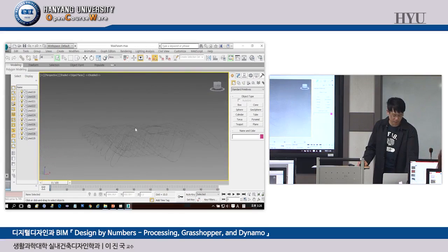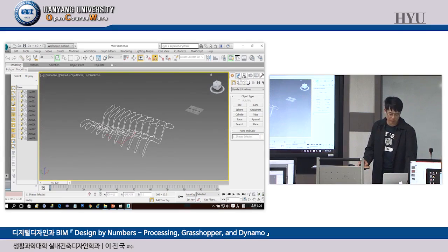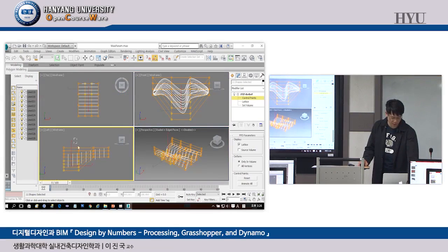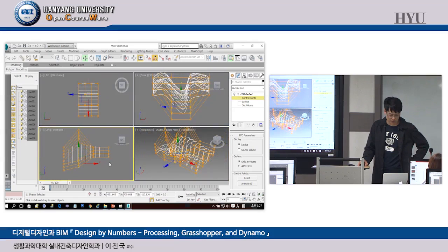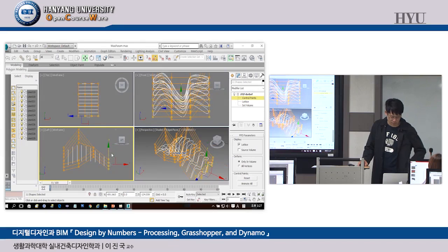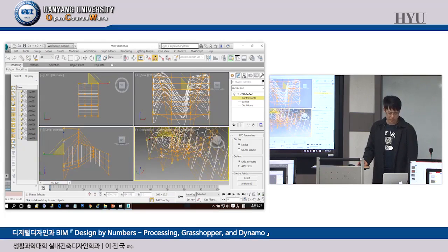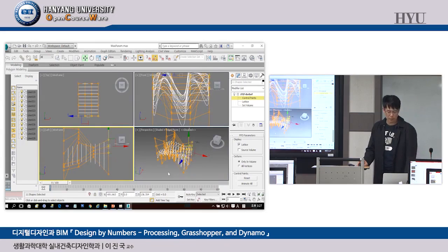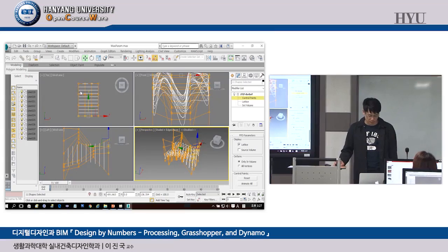Okay, in this view, you can find this kind of geometric shape, okay? And after selecting those things using control points, let me show you how to make some changes. Click control points here, and let me move or rescale, okay? So try to find out what's going on, okay? Like this. How about scale? Like this. So take a look. As you know, FFD is really, really useful when you make changes like this. How about this?